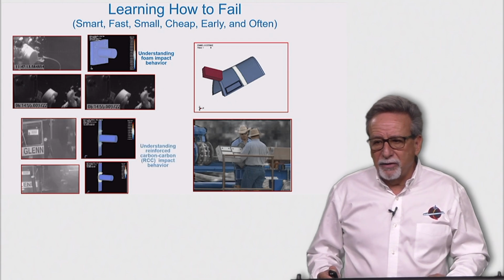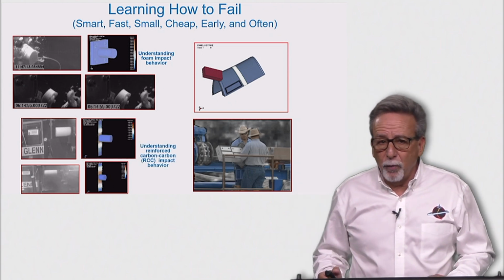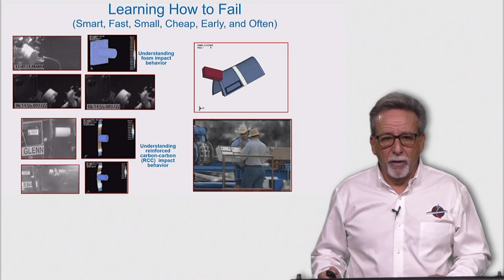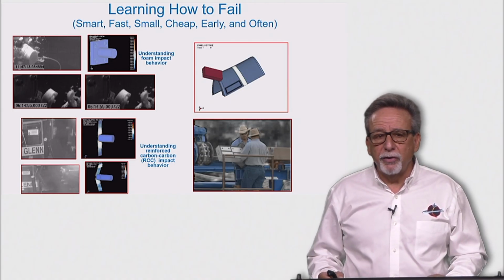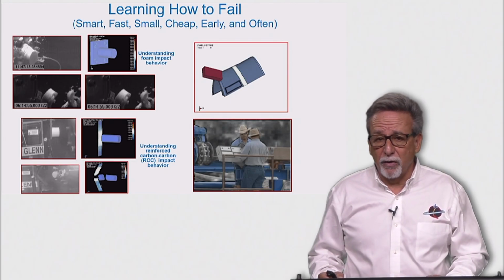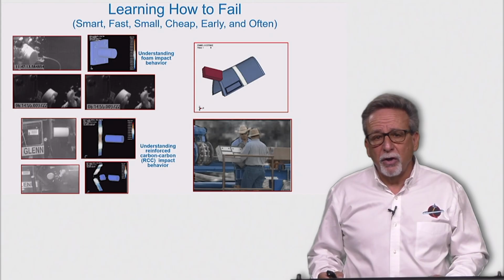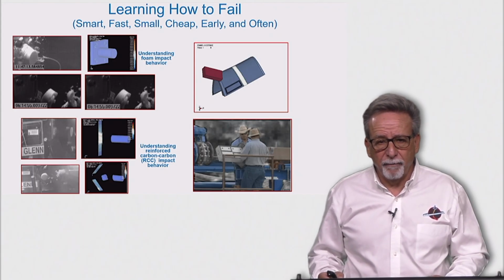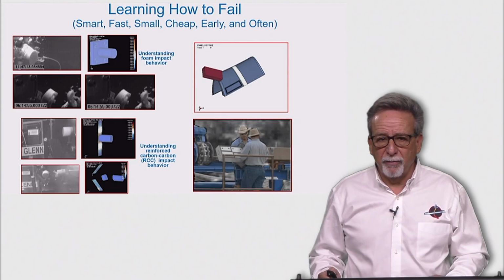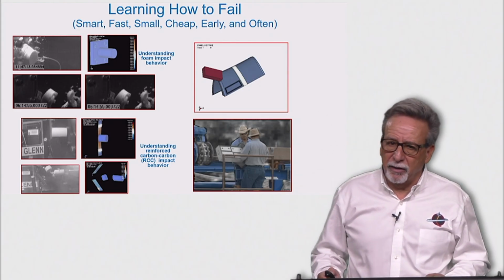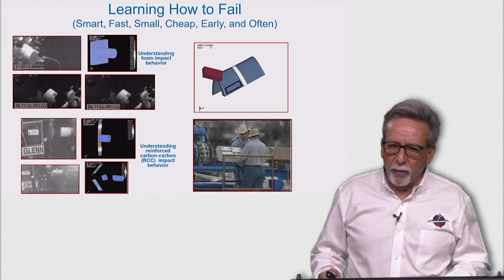We also had to understand the behavior of ET foam impacts to RCC materials that you see in the lower left corner of this figure. What material models do we use to predict deformation, strains, and stresses of the RCC target? And what failure theories would we have to use in order to accurately predict failure and damage to the RCC? We test the failure, we validate our modeling techniques, as you see, and then we use what we learned